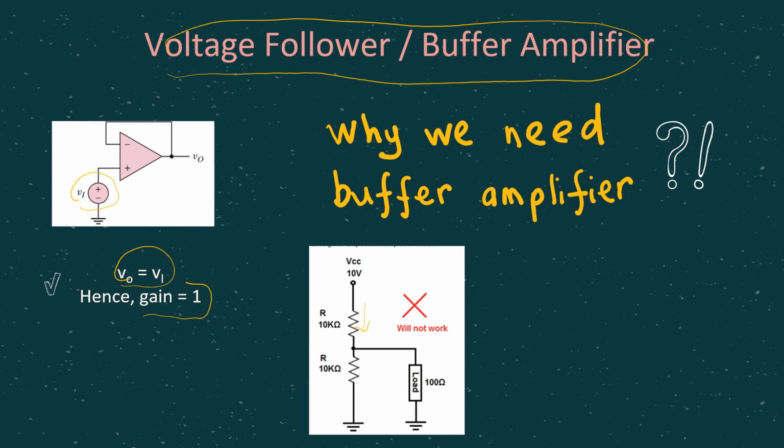When you have two parts like this, remember V equals IR, where R is small, so a small voltage drop will be here across the load. So if this load is connected to any LED or diode, there is not enough voltage to turn on the device, meaning the circuit will not work.